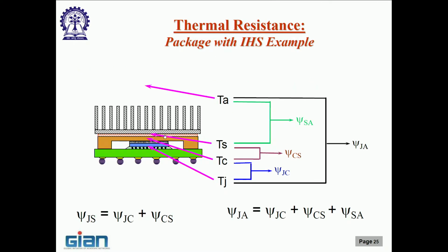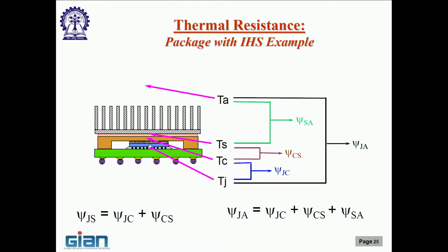Putting a thermocouple over here and making sure that the positions and the sizes are such that the heat flow path itself is not impacted. Remember, these thermocouples, when you introduce, these are obstructions to the heat flow path. That itself, the very introduction of these thermocouples is going to disturb the heat flow path. So, you have to be very careful as to where you are putting it and have an estimate of how much you are disturbing the heat flow path otherwise. So, these measurements are not easy.